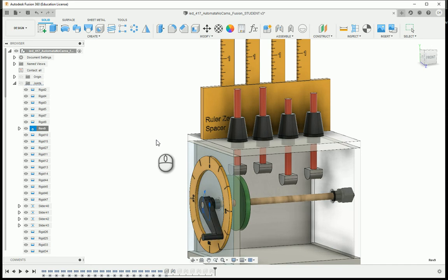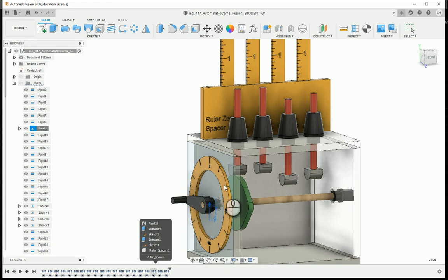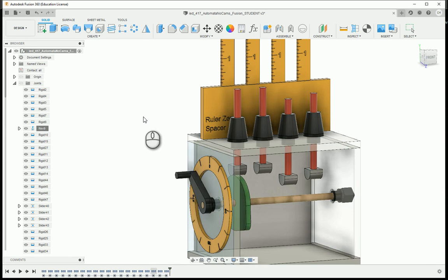But other than that, this is how you can look at the groups, find those down in the bottom, get your cam measurements, and create your motion graph. Even if you create a custom cam that would fit inside the box and you're not sure what the motion graph would look like, that's how you can generate those, and then you can create your own custom cams, modify them, or do anything as such.